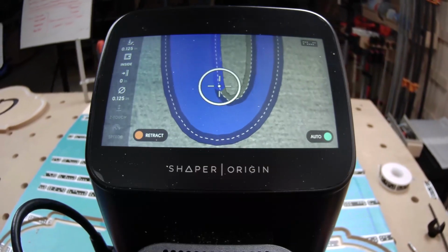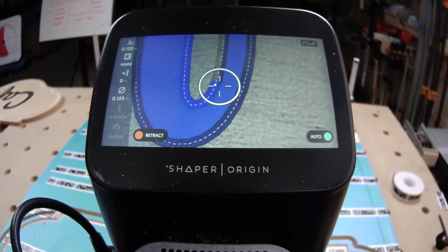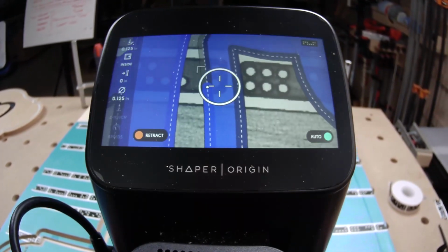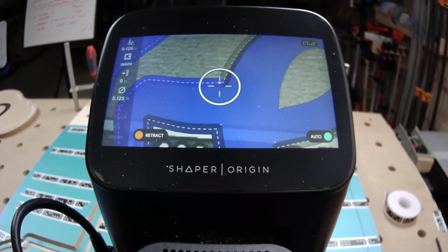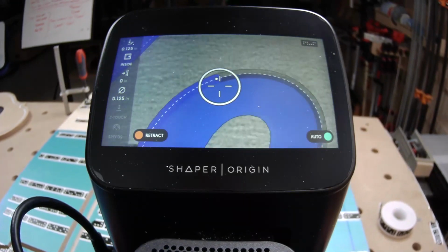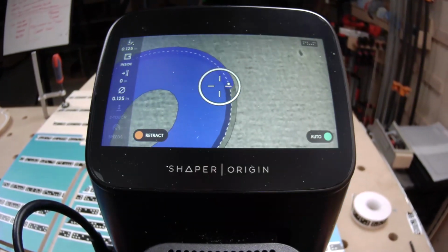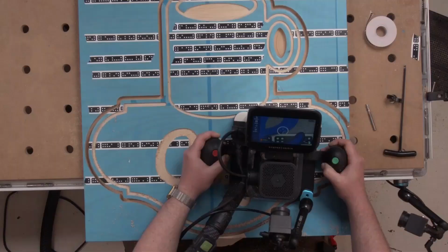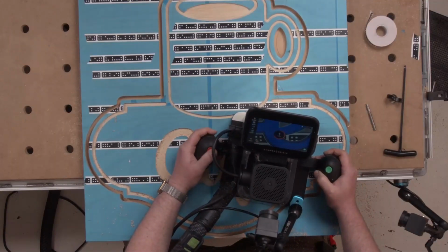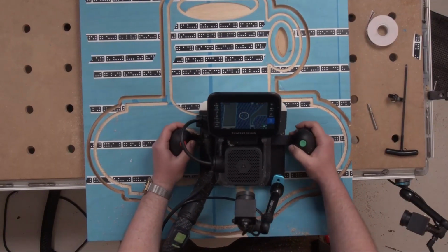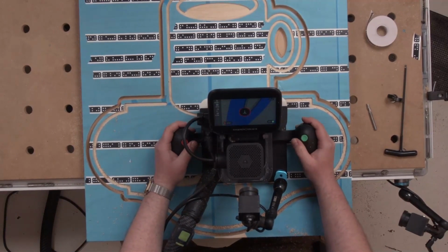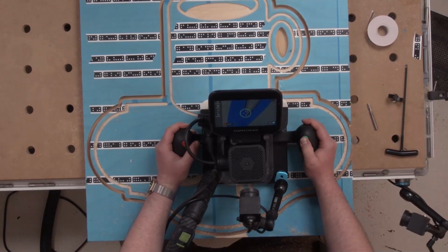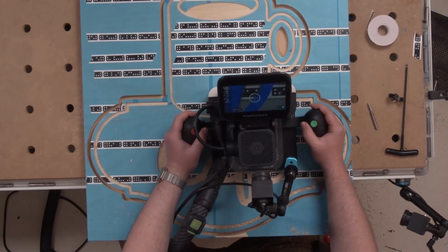But the deeper you go, as that epoxy cures, it's going to give off heat, and the deeper it goes, the more heat it gives off, and so the slower you want that chemical formulation of the epoxy to cure. So this show in particular is not an epoxy show. We've done a couple in the past, but that is just the one thing to look out for. Make sure that the epoxy that you use, and there are a ton of them out on the market, matches the thickness of the sign that you want to make.